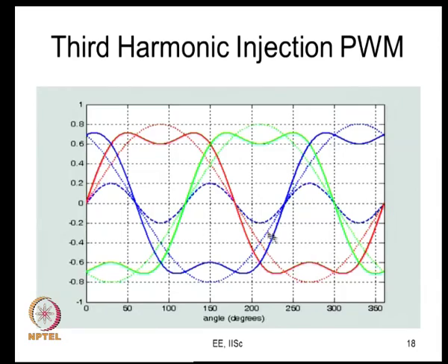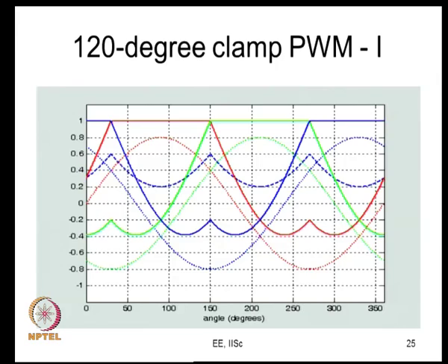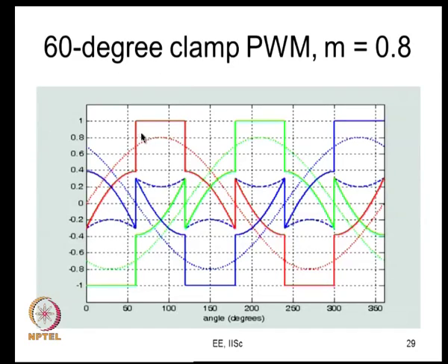So, the phase switches everywhere, whereas if you go to some bus clamping PWM method, let us say here the phase does not switch. So, during this time the switching energy lost in that phase is 0. Similarly, during this interval the switching energy lost is 0. If it so happens that the current also has a peak here, then you are never switching the phase when the current is high, and therefore, you will save a significant amount of switching energy loss, particularly when your load power factor is high. So, that is really the essence now.